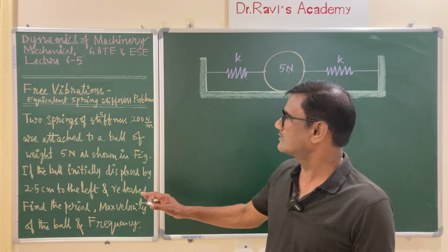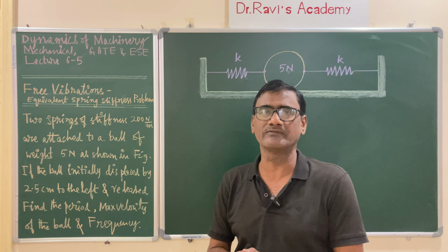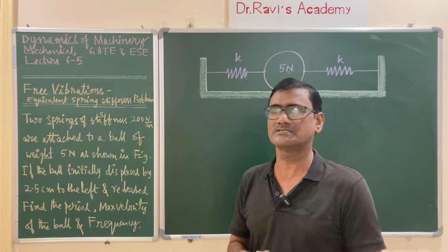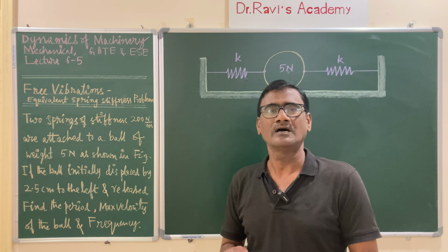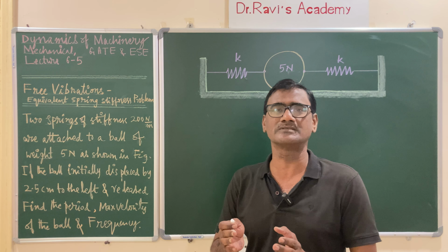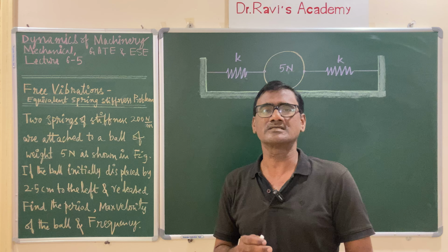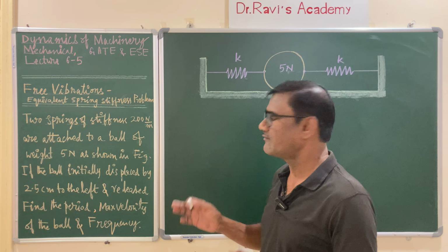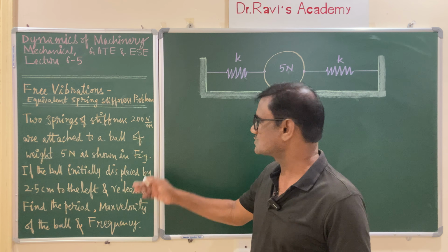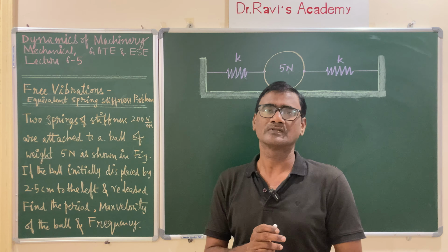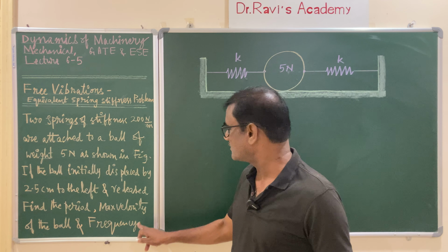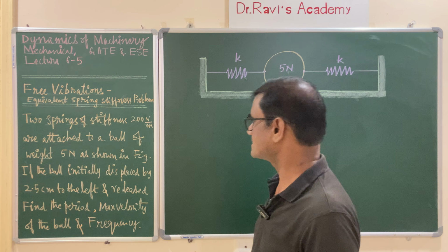As a mechanical engineer, we are trying our level best to calculate the frequency of the systems. And as you know, resonance occurs when the external frequency matches the system frequency, and unwanted or violent vibrations take place. The amplitude of vibrations violently increases, and the system will collapse. That is the reason, to avoid the resonance problem, we always focus on determining the frequency of the system, so that we can design our system to avoid resonance. So keeping that in view, we are involved in finding out the frequency of the systems.